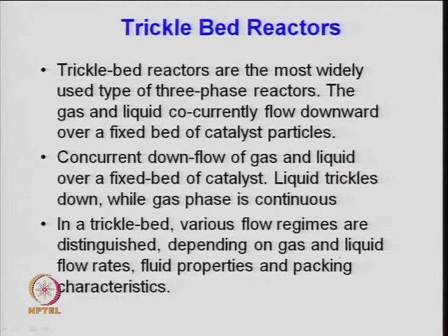Especially when mass transfer or solubility is an issue, say hydrogen is difficult to dissolve in kerosene. So, for these kinds of reactions you need high pressure to make it soluble, and it depends upon the concentration, the solubility and the type of solid which is your catalyst.